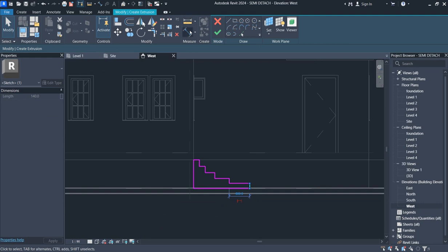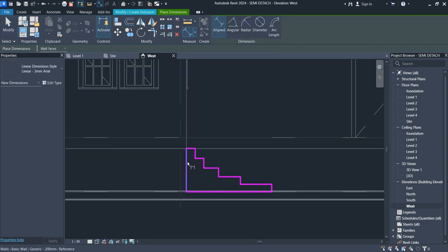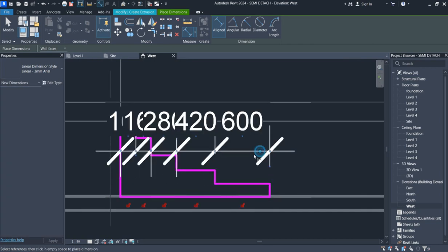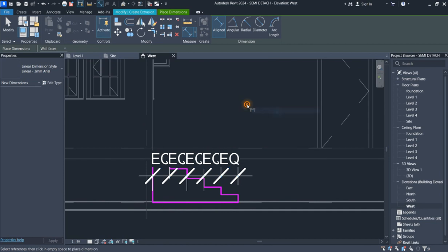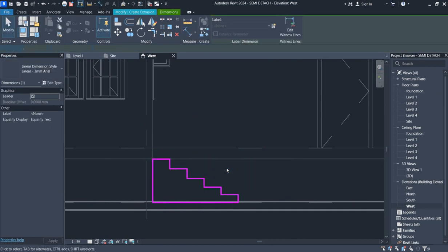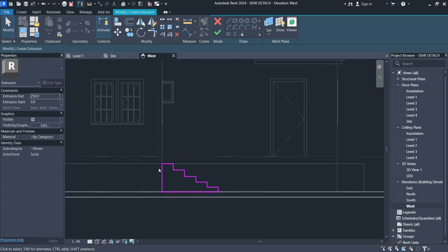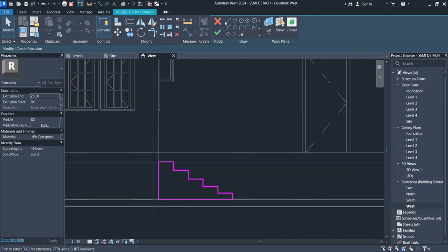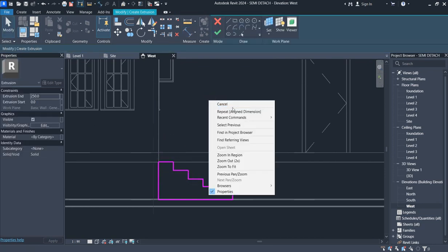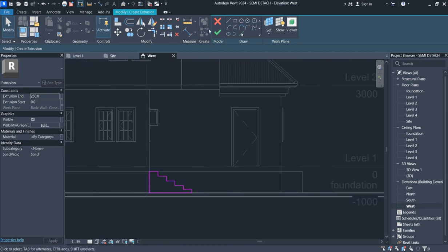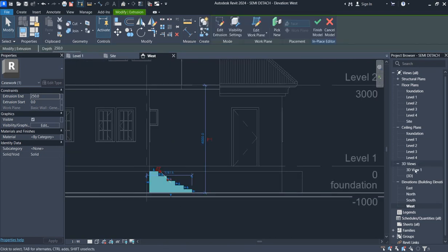So what you do is you select this and use the dimension to make your values equal. So you click here like this and look for the equal expression. The equality will bring everything to be equal. If you check the total dimension of this place to this place now, they're equal. Check here to here to there. Can you see? So that's how you do it, as quickly as possible. Click finish. So click finish now.